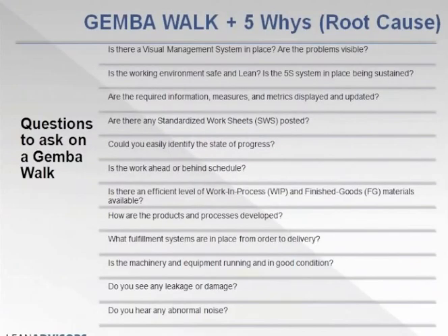Out there, what should you be looking for? Well, you should be looking for those visual management systems. Are problems visible? Remember I said earlier, make things ugly? Often I'm asked when we set up a work center, can we set this up so that we can make 10 extra pieces because we have a high scrap rate? And my immediate answer to that is always no. Set it up in one-piece flow. So that if one breaks and you have a defect, it's ugly. Visual management, it's ugly. When you've got 2 sitting on a bench, it's only built for 1, that's ugly. That's time to jump in, fix the problem. Don't hide the problem with another piece. Fix it and move it.